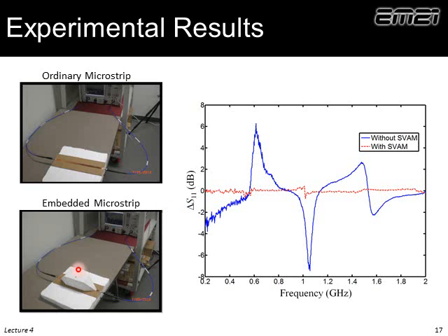The next thing we did is we took, in this case, a metamaterial, a spatially variant anisotropic metamaterial, and you'll see this dark spot right in the middle. That's a hole that we could drop the metal ball down. And what this does is sculpt the anisotropy around the line, and it essentially pulls the field in this upper right direction, pulls it away from where this ball would be so that it doesn't experience the ball. Well, when we put this in place and we drop the ball, bring it out, drop the ball, this red line is the change in the reflection, or the S11, when we do that, and we can barely measure any swing in the S11 parameter. So what has happened is this SVAM, spatially variant anisotropic metamaterial, using anisotropy, has essentially isolated that microstrip transmission line from a metal ball.